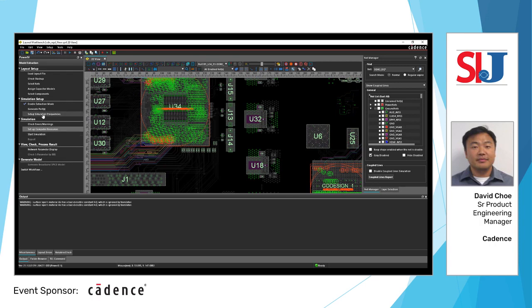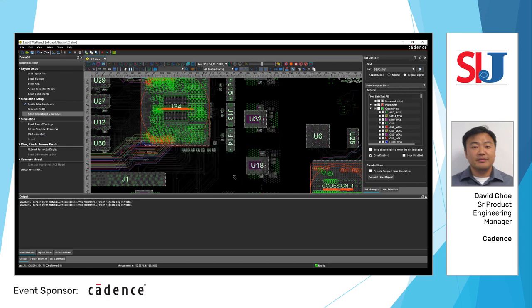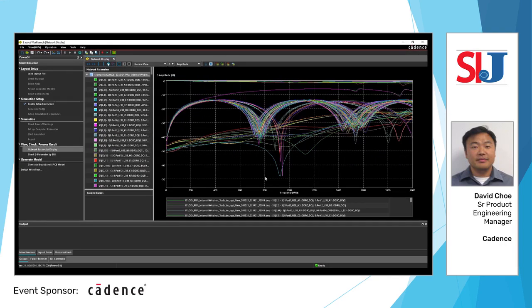And the next thing you do is start the simulation. I did forget the step of setting up the simulation frequencies. You can easily just change that by going to something like 10 gigahertz, press OK. So once you start that simulation, you'll end up with results that look like this. And in this specific case, I only ran from 0 to 2 gigahertz. This is the same database, but now that I have these results, I can pass it off to Jared.